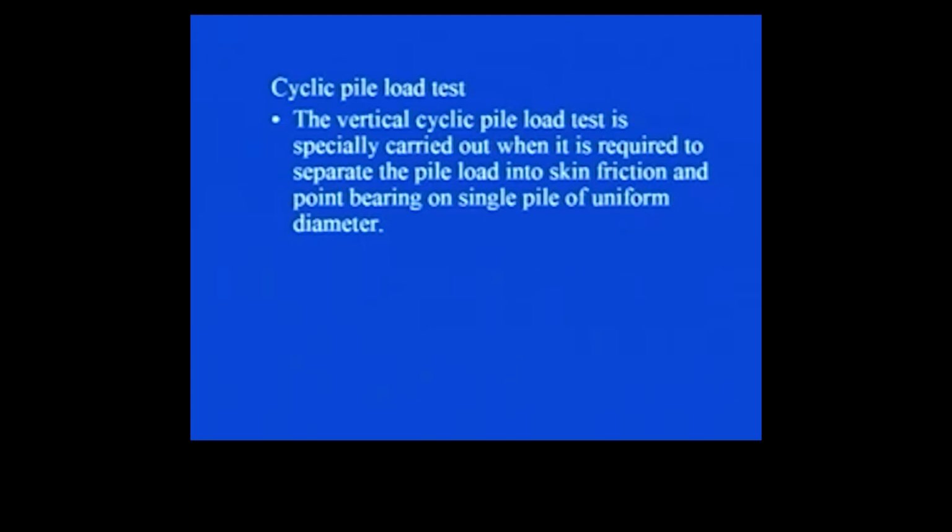See, many a times it becomes necessary to know what exactly is the amount of the load coming from the superstructure to the pile that is getting resisted by friction resistance, and what exactly is the amount getting resisted in point bearing. When you need to know these two separately, then usually the cyclic pile load test is carried out.